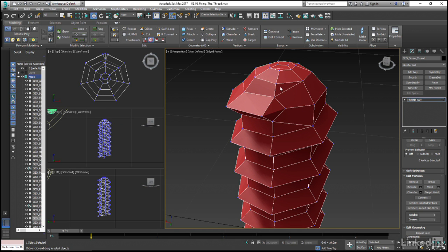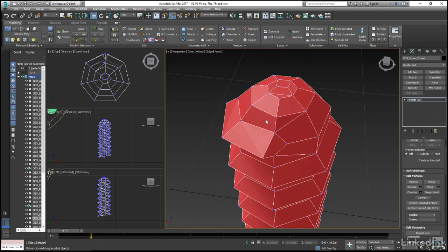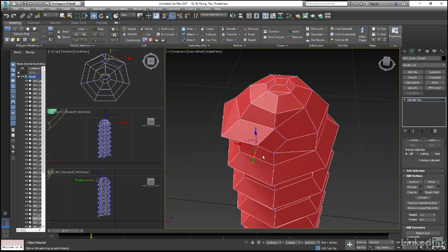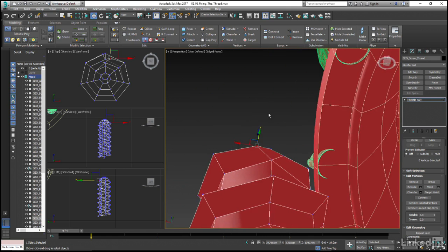To finish things up here, I would like to blend the vertex at the tip of the thread back into the body of the screw a little more. You can see at this moment in time that we have quite an abrupt termination. And so, let's select the vertex at the tip, make sure that the Constrain to Edge option is engaged in the Edit panel, and slide it back a little in the x-axis in order to keep the slope of our spiral intact. And then, after disengaging the Constrain tool, push back a little way in Y, just until we are happy with how things are looking.